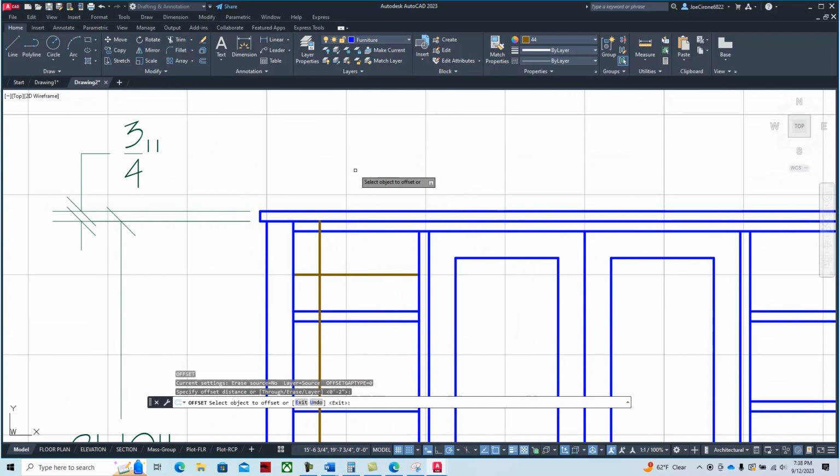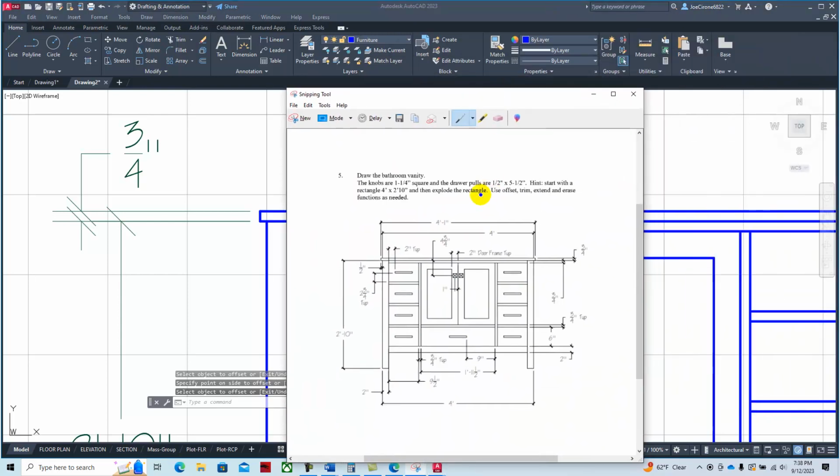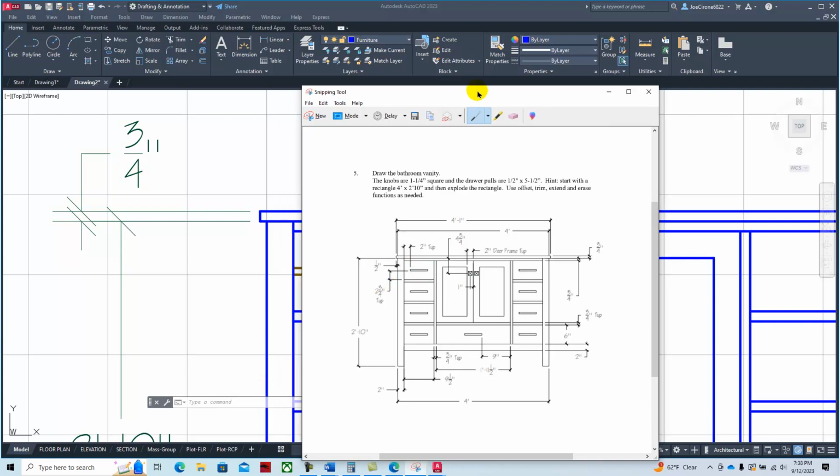And then when you offset those, it'll remain the same colors and properties. So I can offset half an inch for the thickness of the handle, and then the other length was 5.5 inches, so it's half by 5.5 inches. And this was our construction here.